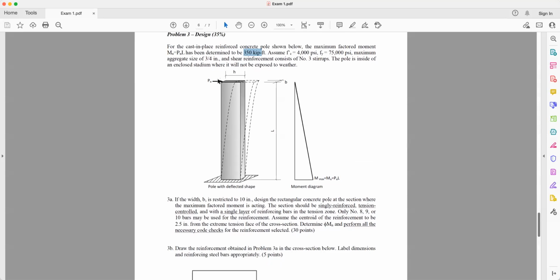Now, pay attention. If the force is pushing the top like this, right? So at the bottom here, the left side is seeing tension, the right side is seeing compression. If you don't understand that, go back, review your mechanics materials, okay? So if the beam is pushed in this direction at the end of it, the left side, on your left as you face the paper, is in tension, and the right side is in compression, okay? So reinforcement wise, the reinforcement should be on the left side.